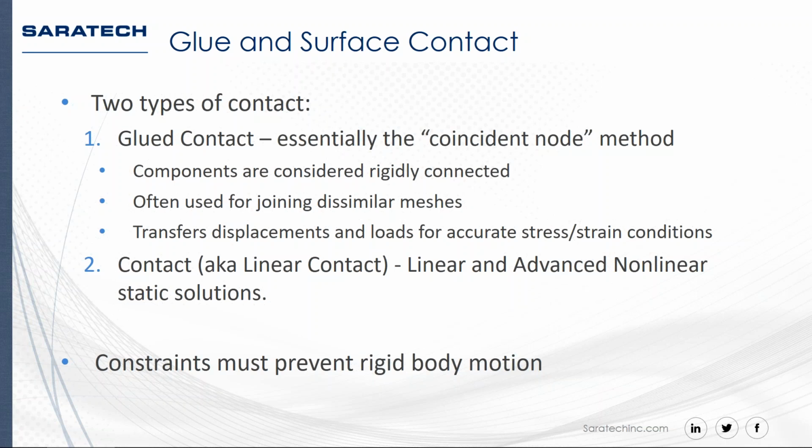Now, the second type is contact, often referred to as linear contact, so it doesn't get confused with the surface-to-surface contact, which is nonlinear, like I mentioned. This linear contact can only be used in the linear solutions like linear statics, modal, and so on, and also the advanced nonlinear static solutions, but not the basic nonlinear, like I mentioned. It's a little counterintuitive, but it's just how it works behind the scenes.